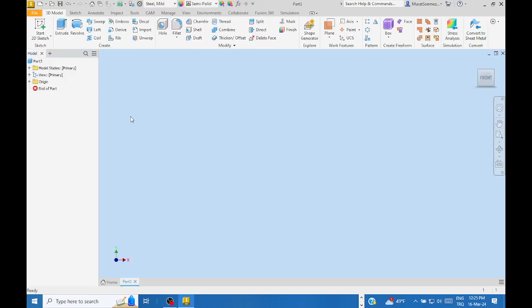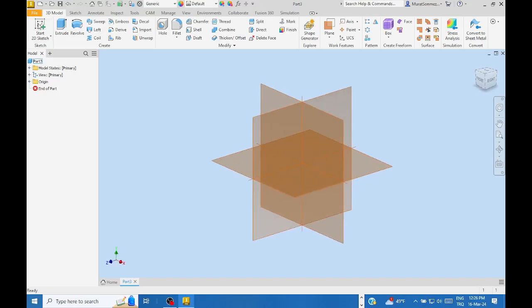Yes, now in the Inventor environment, all the modeling facilities are active to use: creation, editing, and some others. Solid model creation starts from the sketching stage. For a rectangular prism, a 2D sketch is needed. Click on the Start 2D Sketch button. You know, the ones highlighted right now are the coordinate planes defined by the XYZ Cartesian coordinate system.